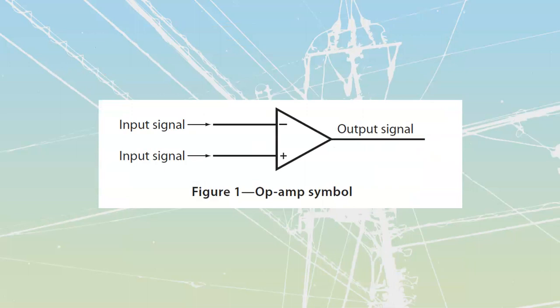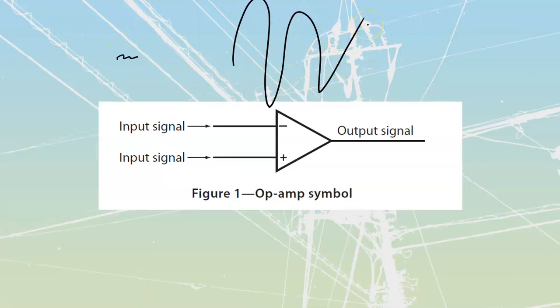Going back over here, because there are so many transistors inside of there, those transistors are going to have cascading amplification. So they're going to multiply together, and we're going to get ridiculously high values of gain. Gain is just going to be the amount of input that I take in to the amount of output that I get back out. We're going to have a gain that is in a lot of cases going to be 200,000, 200K plus. Now this is what the op-amp has dreams of being able to do.